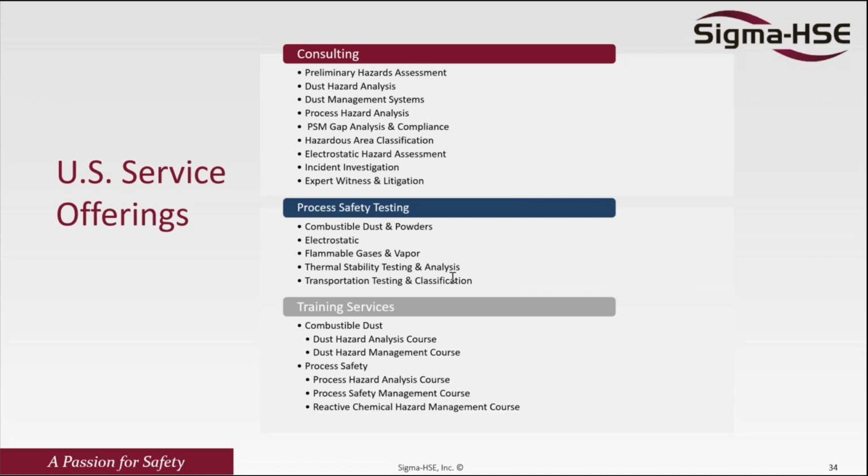We said, what is the difference between grounding and bonding? Bonding is when you have two metal equipment and you connect one equipment to the other, which is bonding. And connecting those equipment to the ground, to the earth, is called grounding. So those are the two differences between bonding and grounding. I can have equipment which is connected to the ground, but if I have another adjacent equipment which is not directly connected to the ground, then I have maybe a metal wire or conductor to bridge that gap, to the same electric potential.